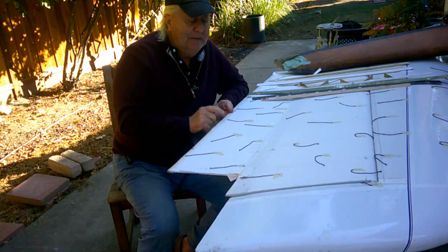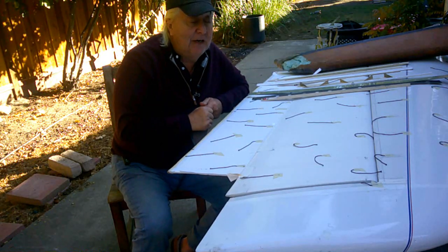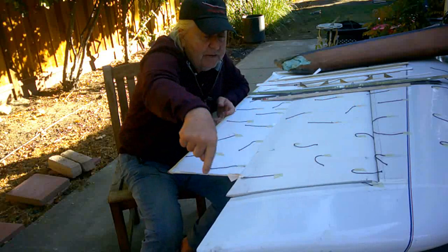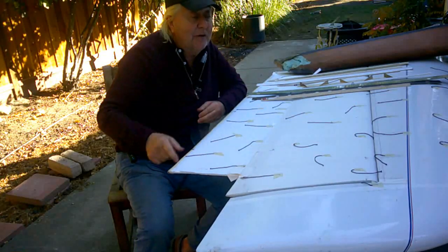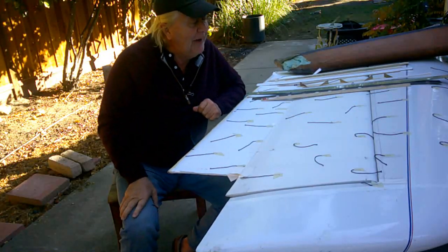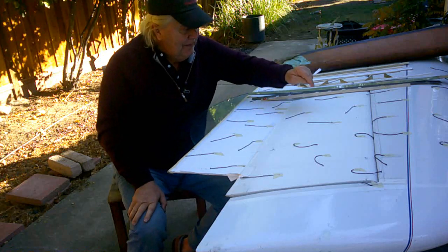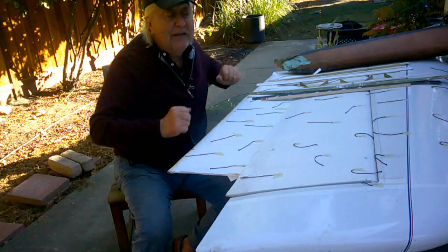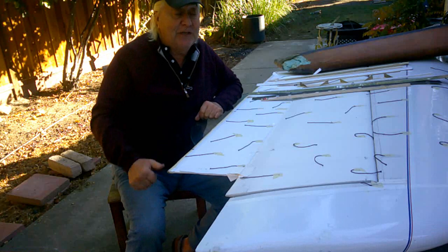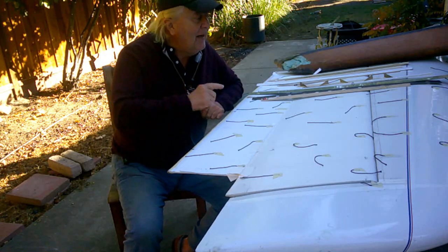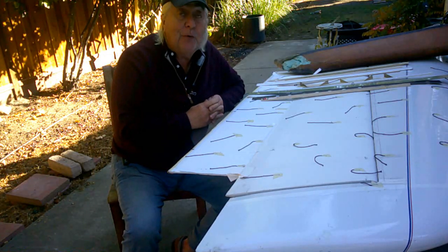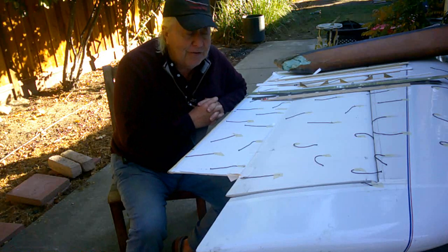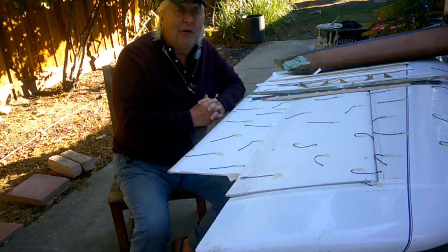So I went back, removed the temporary Elevon extensions, and cut out the Elevon on the wingtips. A lot of work, cut up good wingtip panels, and give me a chance to extend the reverse taper of the Elevon, which I like. The drawback was I now have control surface out of my wingtip where my intention was to never have control surface to help avoid the stall spin problem.